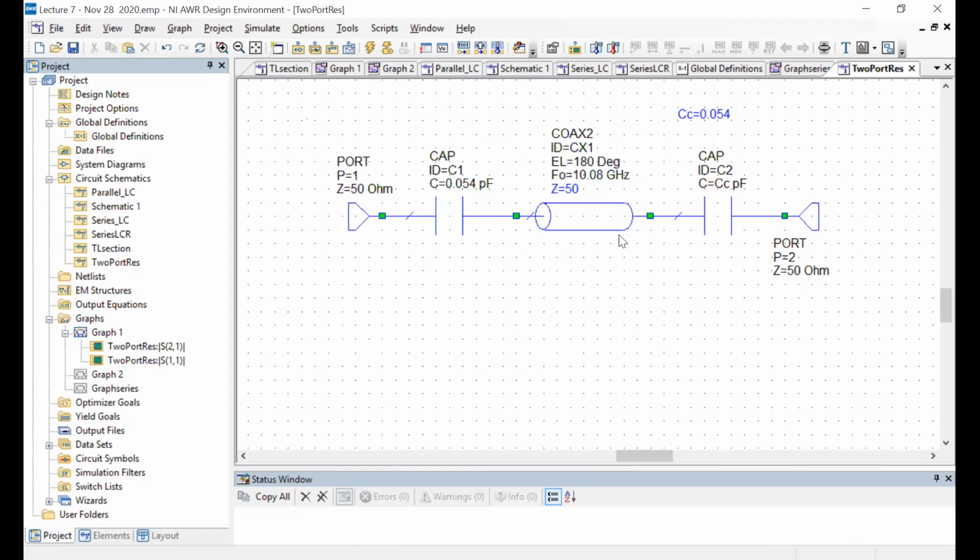Something which all of you must have at least heard about are crystal monitors, which are used to measure thickness of films. It's just a resonator, and as more material gets deposited on it, its mass changes, and that leads to a change in frequency. If you have a calibration curve for mass versus frequency, and the density of your material, you can back-calculate how much thickness of material is being deposited. In fact, this is used in all deposition systems.